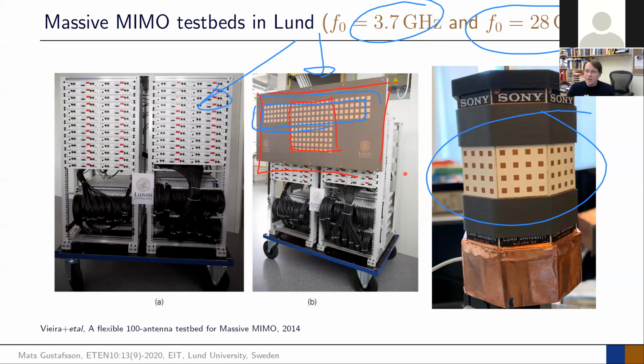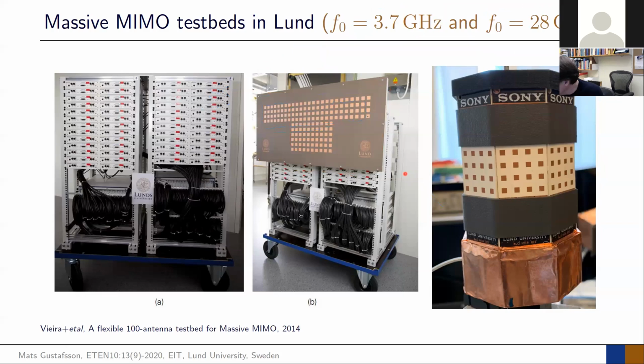And here you can see one of the great advantages of going to millimeter waves, and that's that the physical size goes down. So these are physically smaller structures because the frequency is higher, so the wavelength is shorter, which means that the antenna elements are shorter in some ways. And then, of course, you need to do a lot of processing, and that electronics takes its size also. So that can be done in different ways. But this is an antenna test system for that.